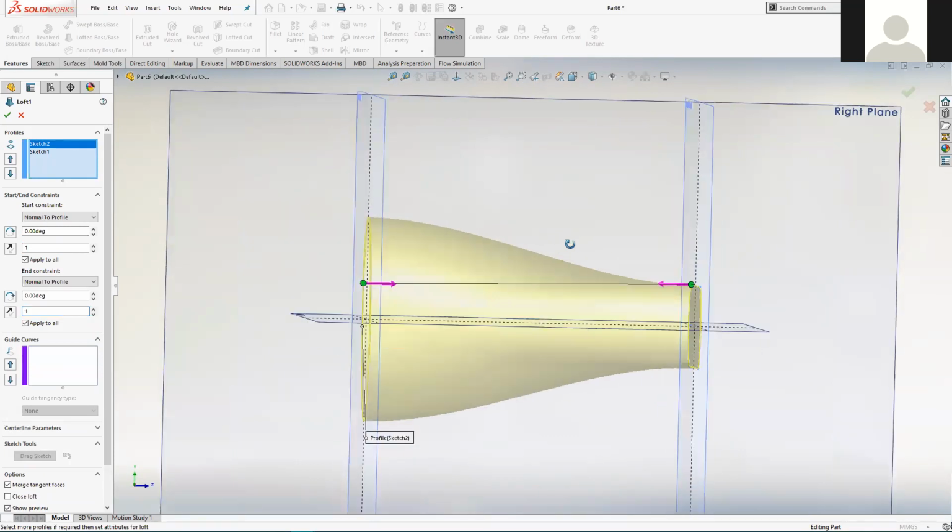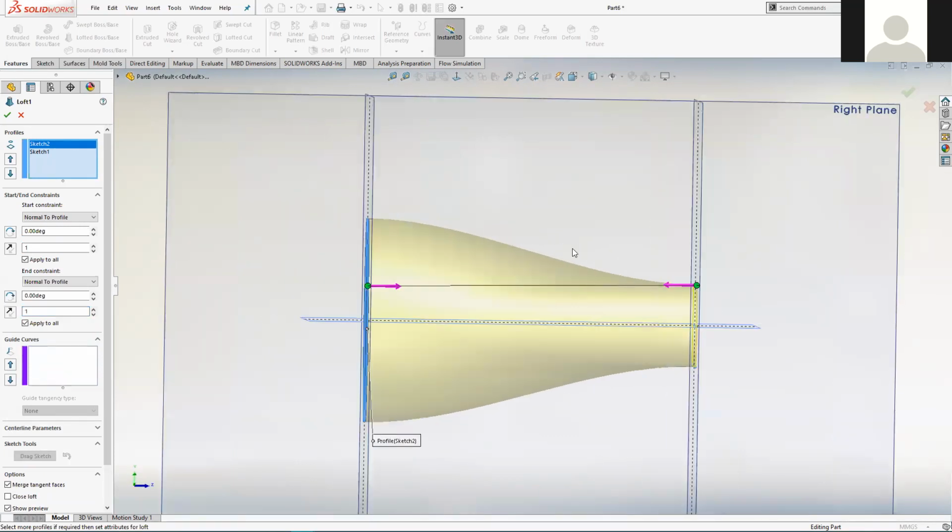Now, another nice little detail in here is you can vary the depth of that influence into the actual loft feature. So this option here, on both of them, the length of the influence. So you can see I'm bumping that value up, and the racetrack shape or the slot shape is having more influence or less influence. I think we've gone a bit too far there.